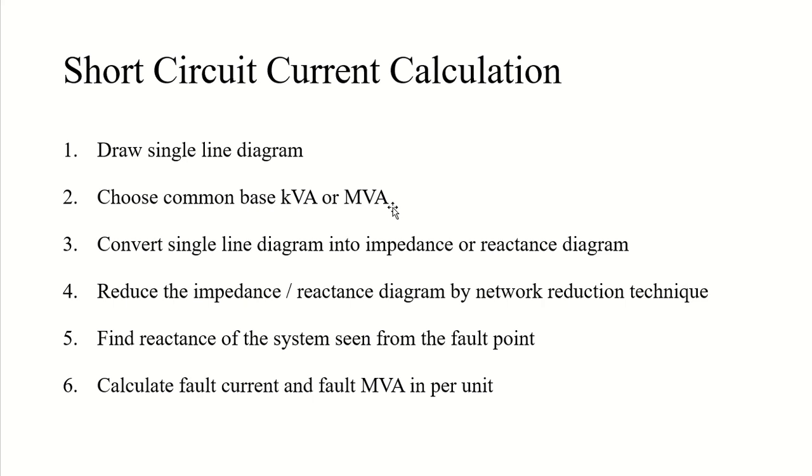The selection of zero phase for one source is arbitrary, and it is convenient in the calculation. You will not need to subtract this value, that value, right? And by assuming all sources in phase and same magnitude, you can neglect the pre-fault load current. Either way, we neglected the pre-fault load current.